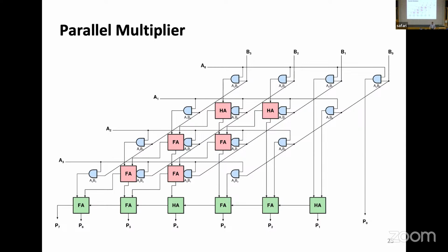Now I realize that this drawing seems very logical to me, but it's not so logical for everyone. So let me try it here. It looks like a parallelogram here, right? So I have the A coming here, A0 to A4. I have B coming in from here. So this is B0 times B4. And then there is the carry propagation coming and generating me the sum.